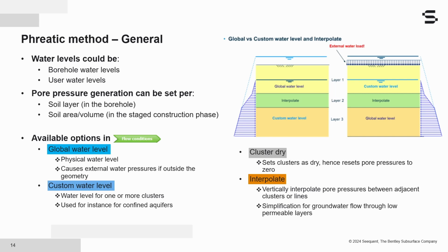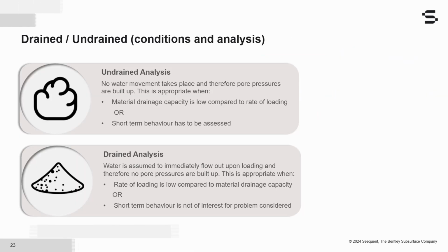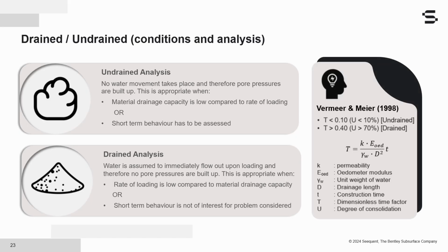All right. One last. Pavel asks, short-term excavation with low permeability. Can you give an example for short-term? A couple of weeks or a couple of months. And could you also give an example of low permeability? It's difficult to tell you exactly a range of numbers that are low permeability or high permeability or long-term, short-term. And that's why I gave you this slide where we have an approximation of what an undrained and drained situation is.